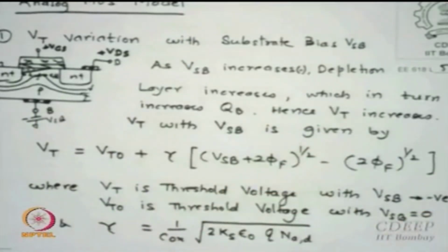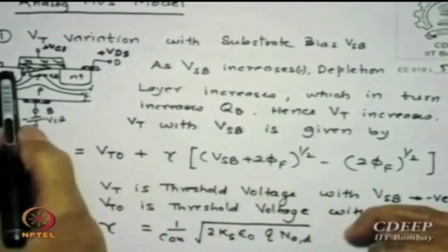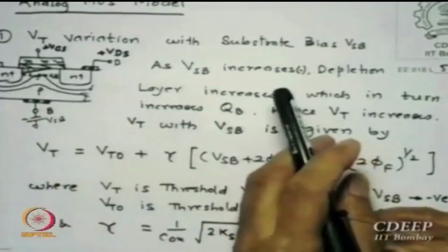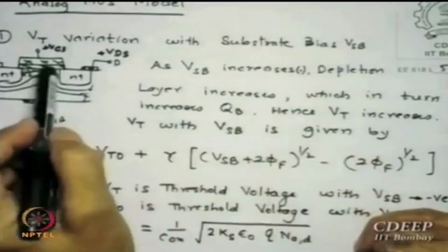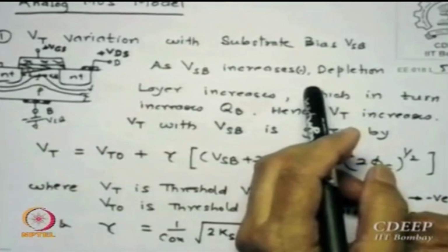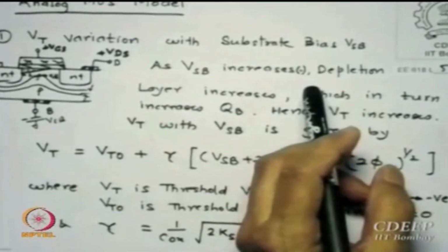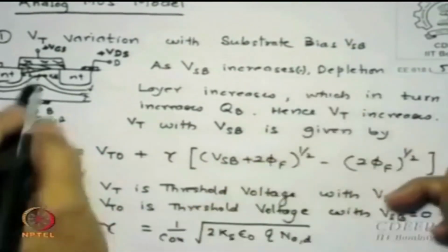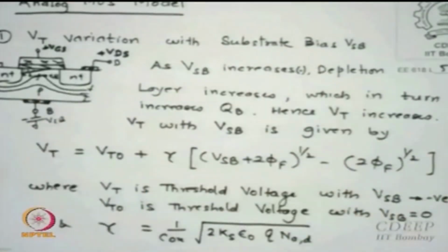But in a transistor, if you look at this transistor, the actual channel length we say is from source to drain, which is channel length L. Once the pinch-off point moves away, the effective channel length is not L now, because the channel exists only for L minus the depletion layer here, is that correct?